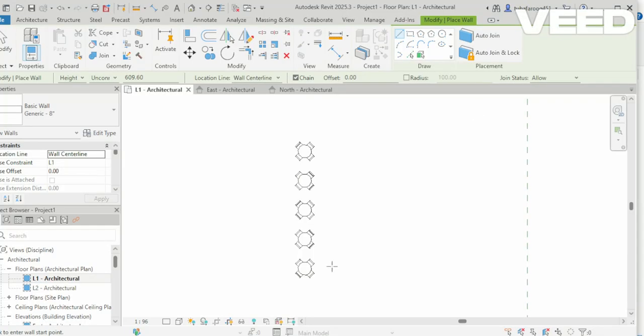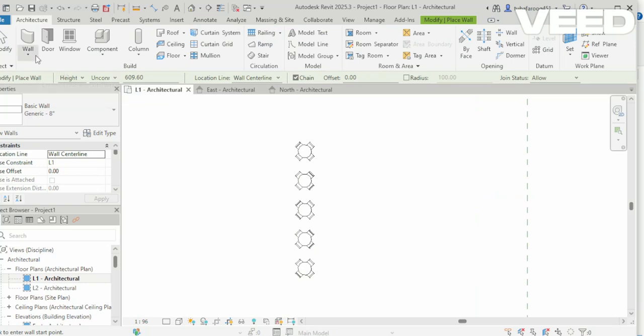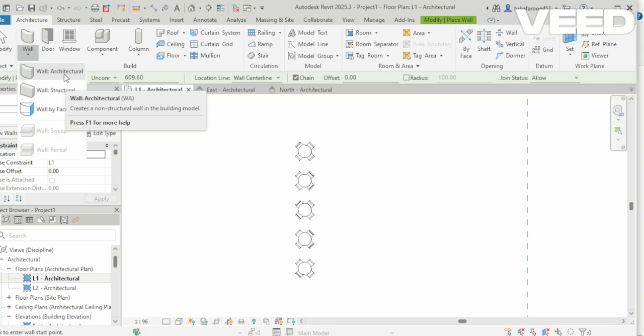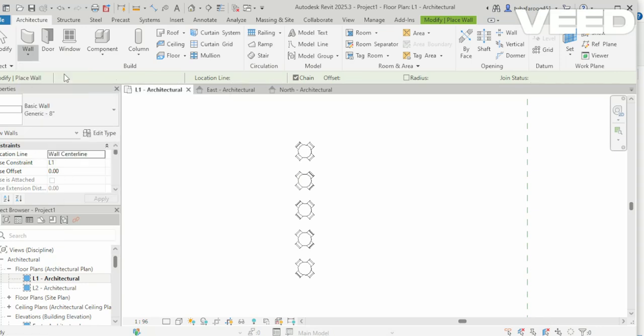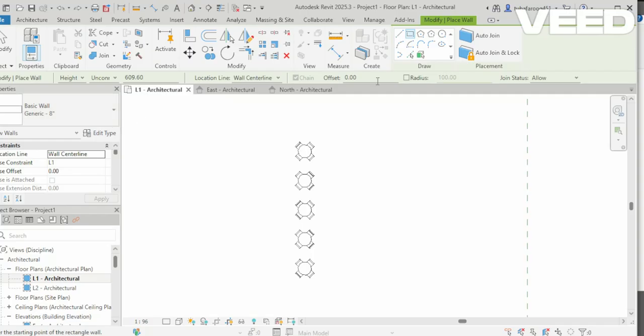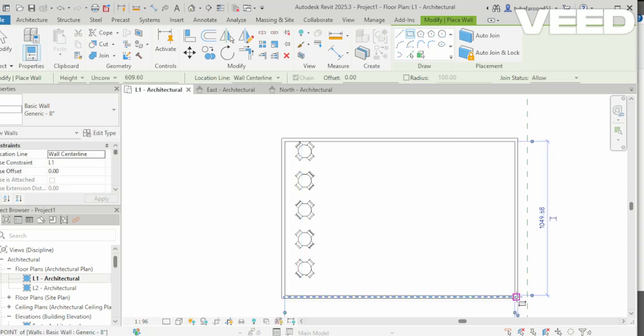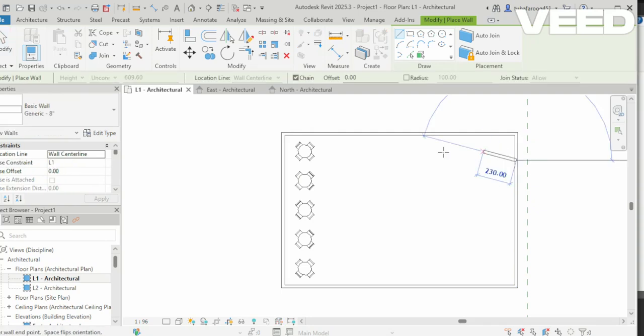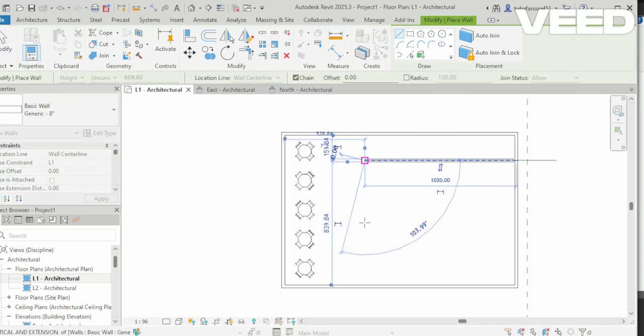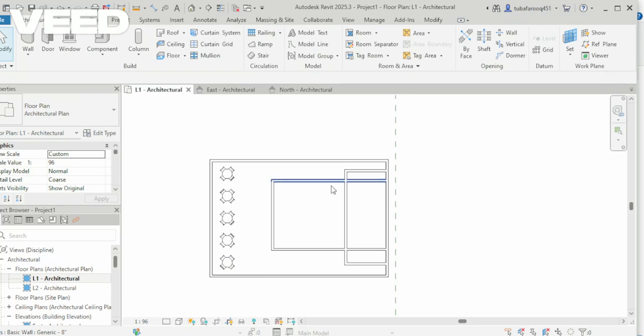The next thing I am going to do is use basic walls. Just go into Walls or you can use the shortcut keys WA for this. Use any smallest one and let's create a rectangle like this. This won't be an actual wall. This is something I am going to use just for the basic dimensions of the cafe. Then use the wall command again and add some more walls like this. Now let's use these walls to get the basic dimensions of our project.